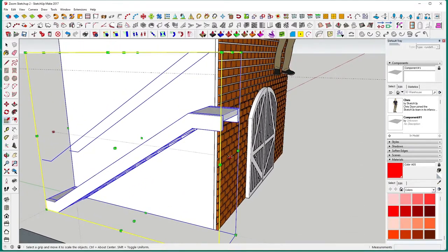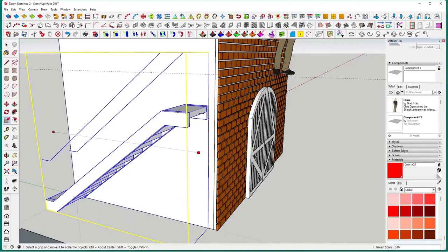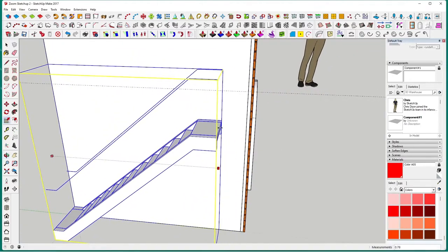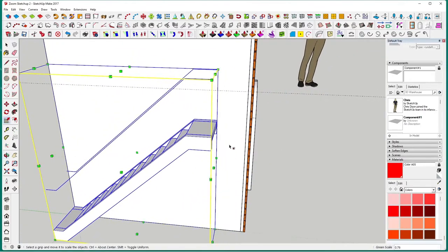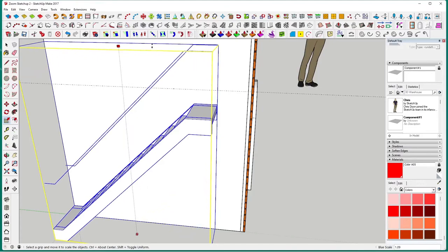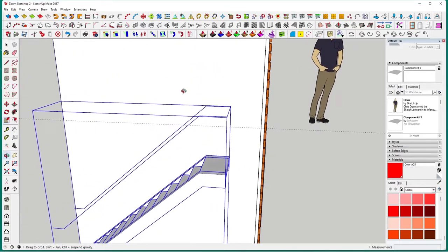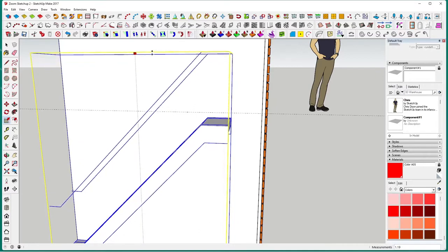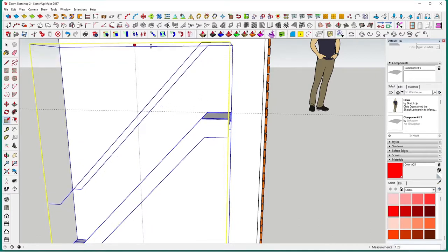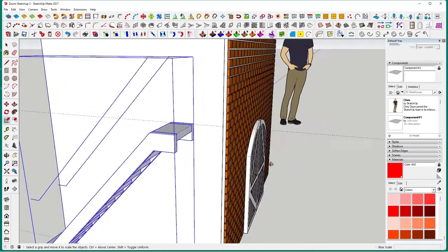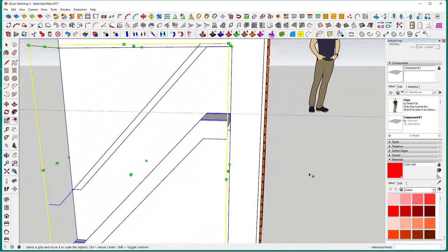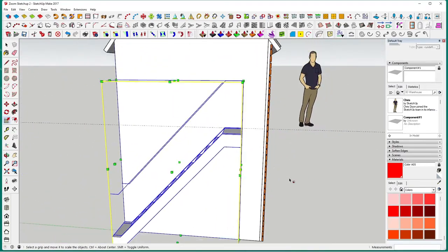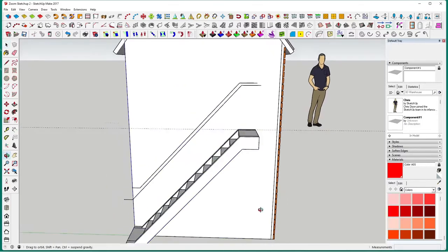We'll click on the stairs and we'll click on this scaling tool. First off, we'll scale it in, but we want to go quite a bit past so we can make a bit of a landing. And then if we click the middle, we'll constrain it to the blue axis, and we can't constrain it to a line because we've got handrails on there, so it's a bit of eyeballing about there. There we go, start of our staircase. Pick tool, click away.